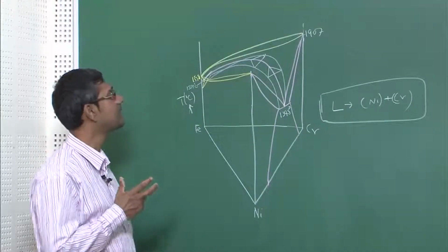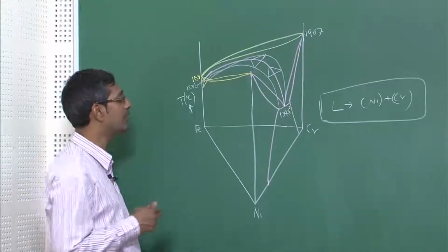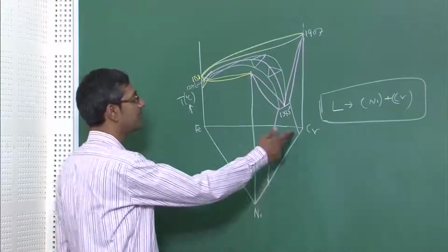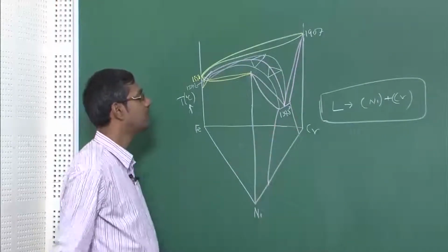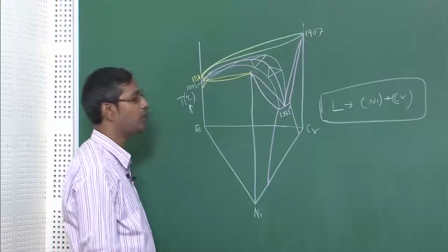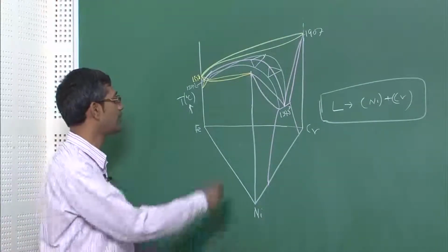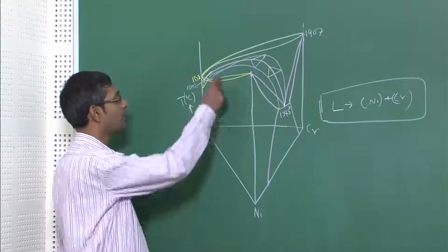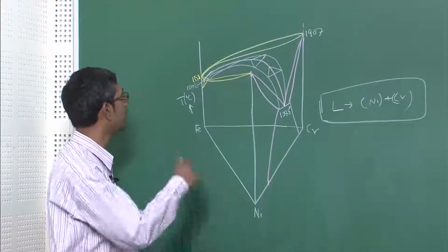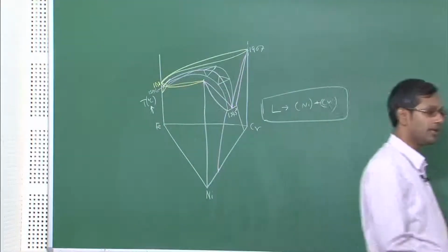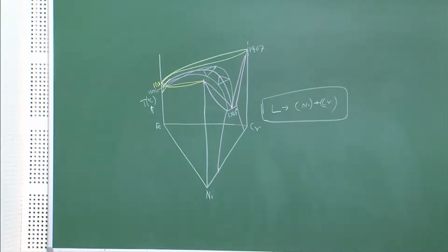So, otherwise this phase diagram is very simple. But on the other hand, if I take alloys which are chromium rich, on this side, they are very easy to handle, but normally God does not give the easiest thing in the world. So, that is why most of the alloys which are stainless steel type will be undergoing the peritectic reaction, and that is the problem. So, I guess it is very clear from the binary phase diagrams what is going to happen.